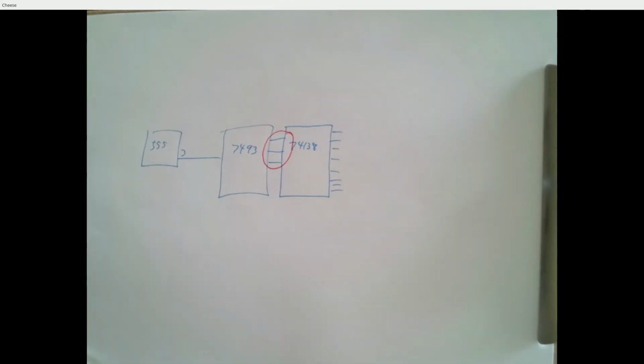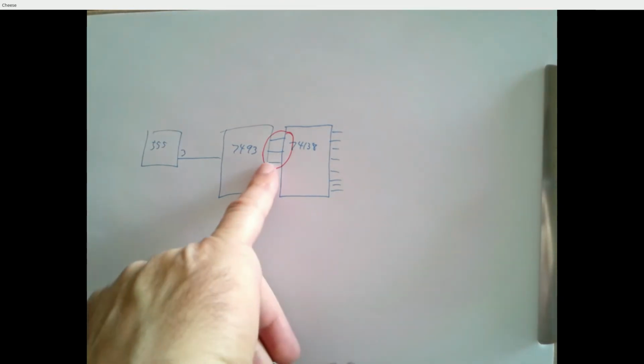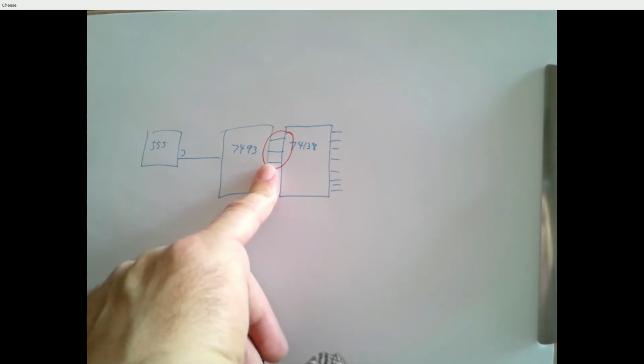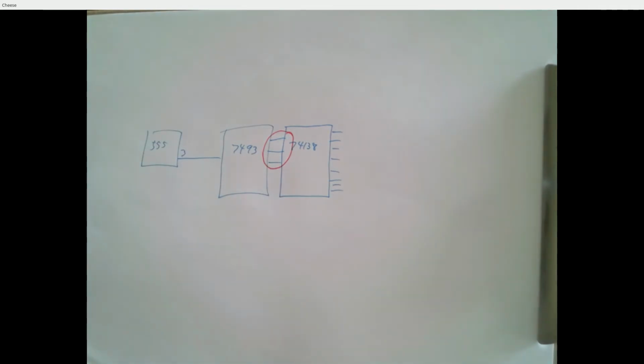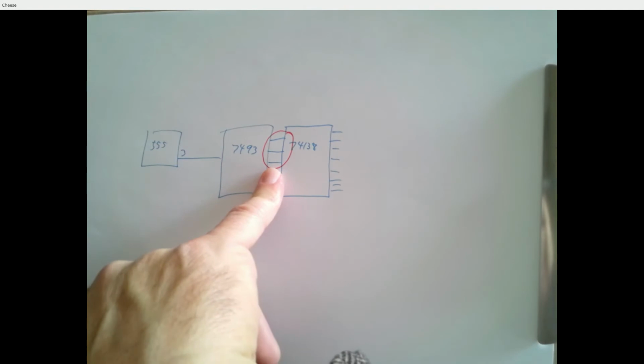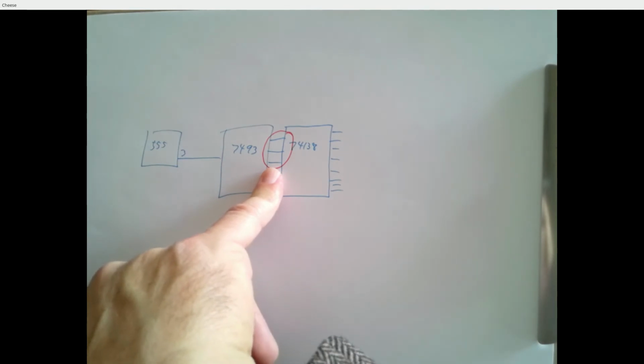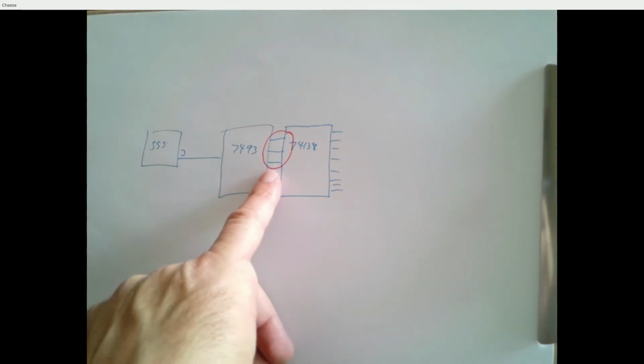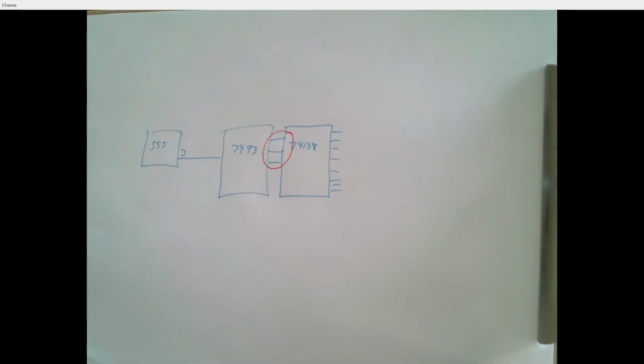So my suggestion would be go directly to the pin on the chip, and put a multimeter there and watch the voltage. Okay. It's changing every second or two, so it'll be slow enough for you to see, and see if that voltage ever goes high, or if it ever goes low, because it's permanently on. And if it doesn't, then there's something weird, but if it does, then you've just got a connection that should be going to that pin and isn't.